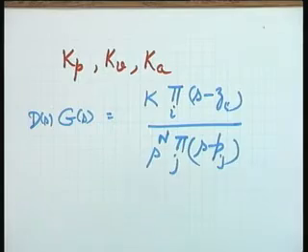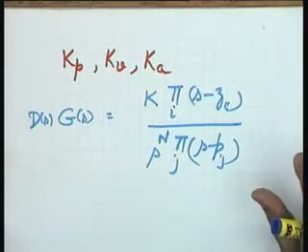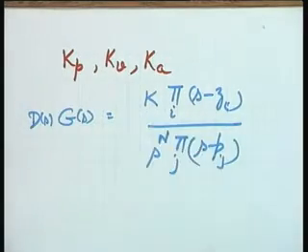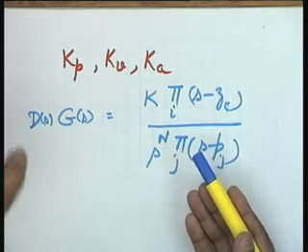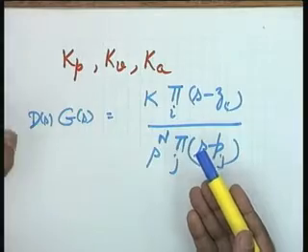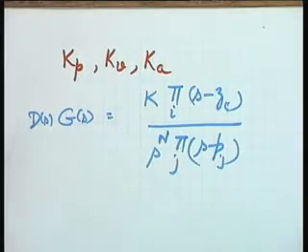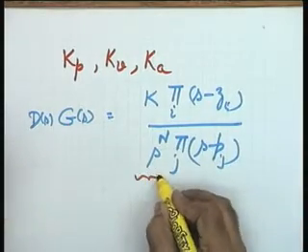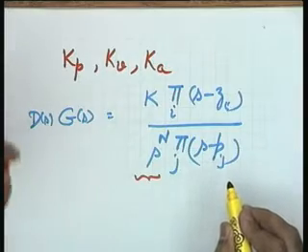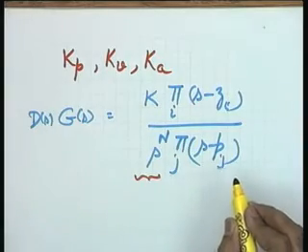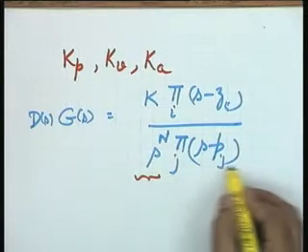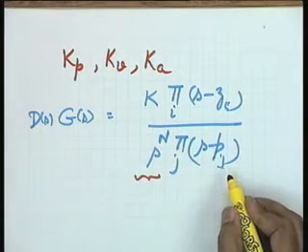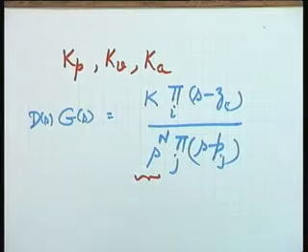All the transfer functions we have handled so far can definitely be put in this particular form: a constant, zeros, poles. The only thing is that specifically the poles which are at s equal to 0 I have taken out, that is all, and my attention is going to be focused on this particular point. That is why the poles which are on the origin of the s plane have been specifically pointed out, otherwise all others are poles. These poles may be complex conjugate poles, these poles may be real poles, and whatever may be the general nature, there is no problem at all.